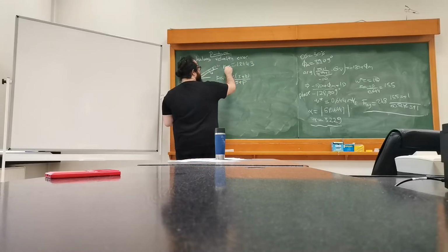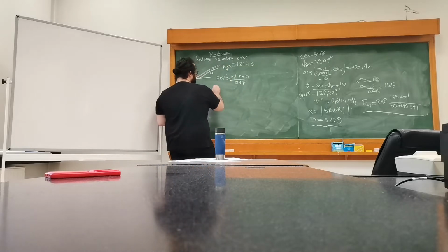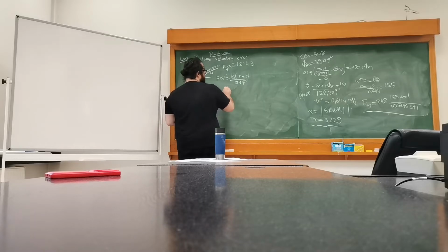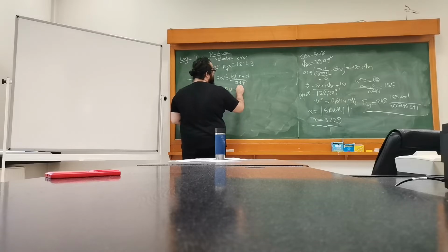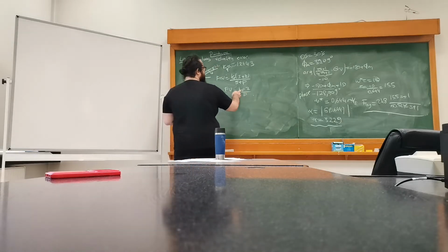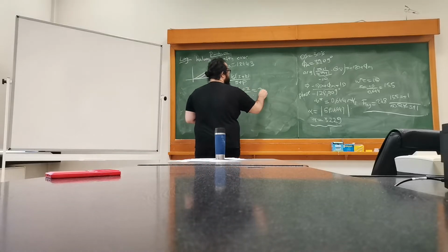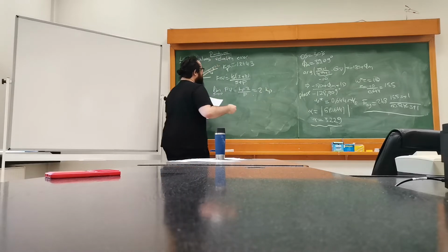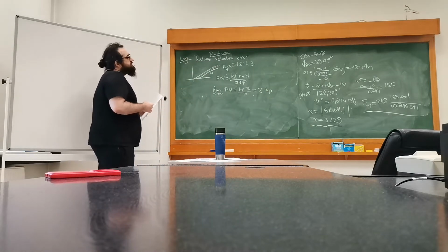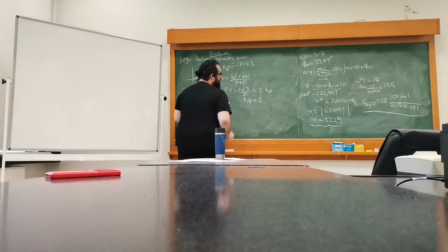I know that the previously designed P-type controller is this value here. And if I look for the limit s goes to 0, F(s), it will basically show me that the end result looks like this. So the gain of the controller is actually Kp, the P-type controller, times c divided by p. And now I want to have the effect that this is equal to 2 times Kp, because of the doubling here. So therefore, I can see that the z to p ratio should be equal to 2.